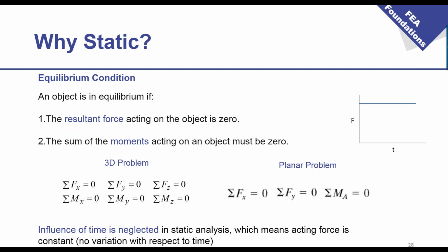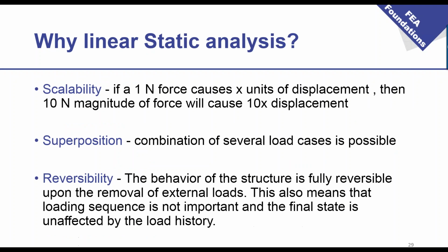So why static? Again, you always have to think about this: the influence of time is neglected here, and this means the acting force is constant and there is no variation in time, and the sum of the acting forces should be zero. So if you consider the problem, the sum of all forces and moments should be zero. If we are working in a Cartesian system, then along all of the axes it should be zero. For the planar problem, the number of equations is much smaller.